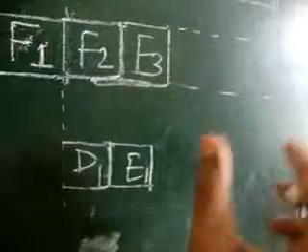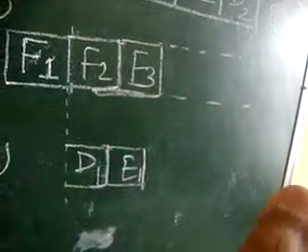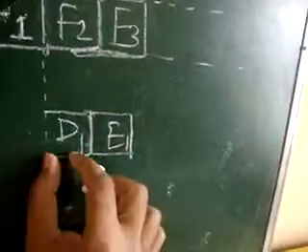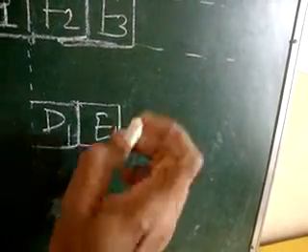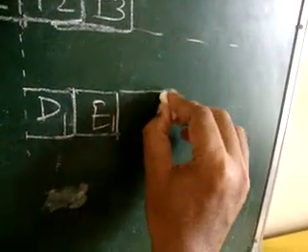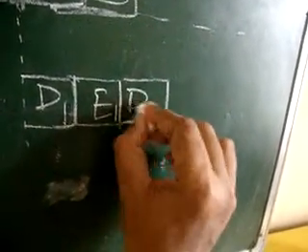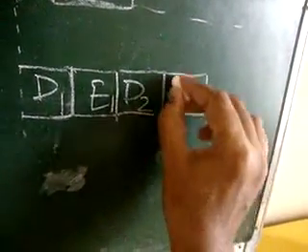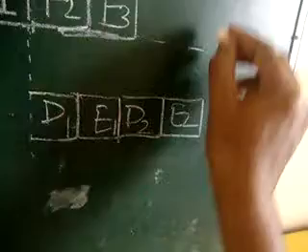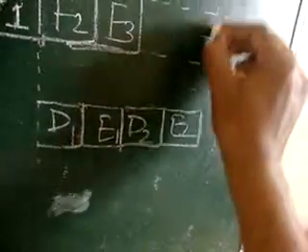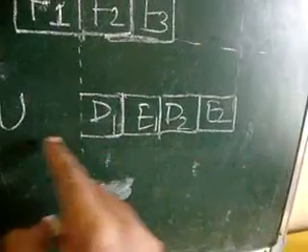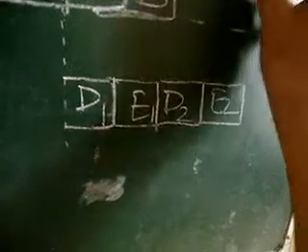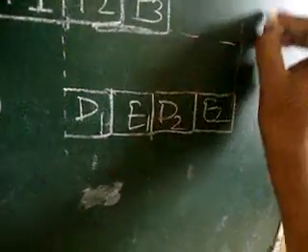parallel, so that if we consider the total time required to execute two instructions, here the first instruction is completely executed. Now decoding of second instruction and execution of second instruction occurs. So in this time slot, you can see that two instructions are completely executed, and this remaining time is the time which is saved.